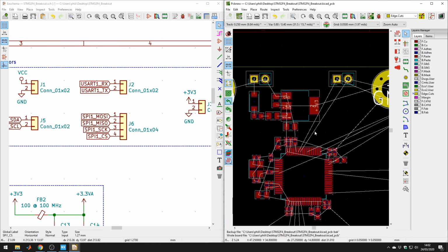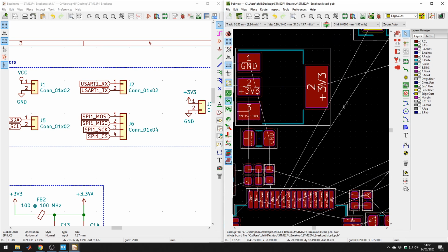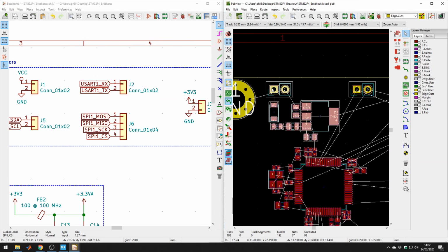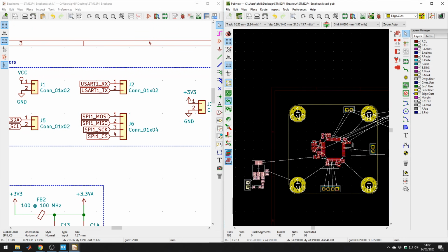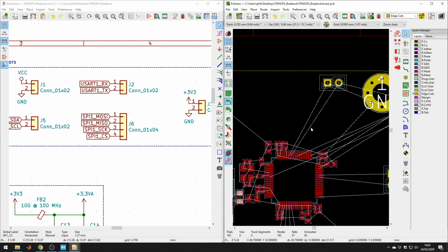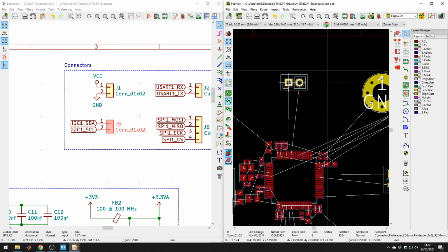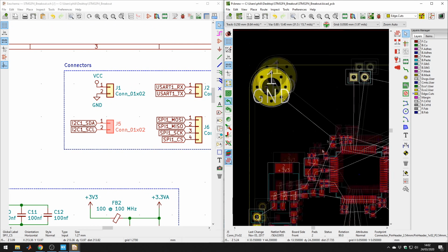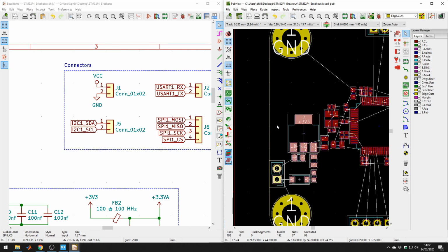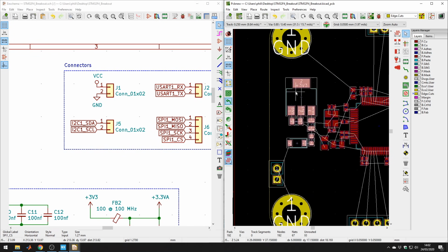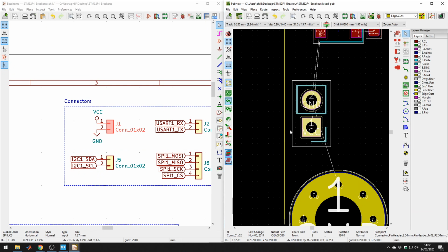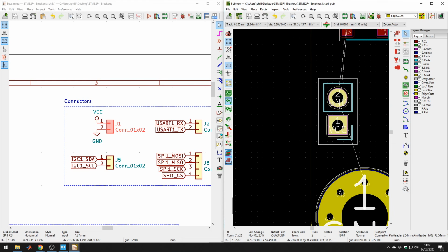Now, one thing which is bothering me a bit is this I2C lines will have to cover quite a large distance. So what I'm thinking is I'm going to move the regulator. Whoops, I hate when it doesn't. Somewhere over here and just redo it a bit, because I want these to be essentially just above it. These lines. This to me looks a bit nicer. Okay, let me just move this regulator over here. The same old thing of making sure the distances are right.